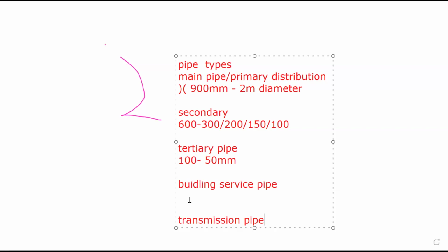Any question? Okay, there's a question on the platform. How do we estimate the volume of water and its sustainability from different sources, especially in dry regions? Well, I think from my small experience, it is pump testing. You know, we don't do pump testing in Nigeria. When you drill a borehole, you're supposed to do a pump test of the aquifer to know if the yield is adequate.